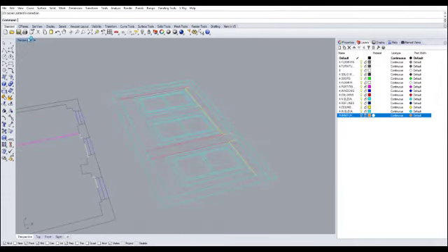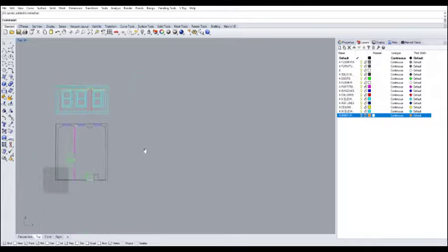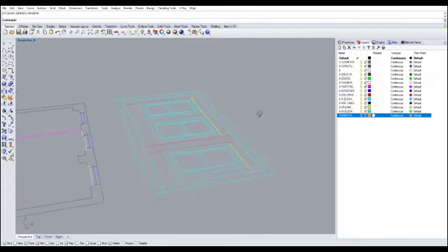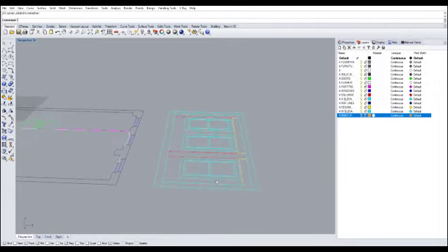So that's an important distinction to remember. When you're on the top view, let's go back, double click. To pan, it's just simply right click and drag. You don't have to press the shift key. However, if you want to pan in the perspective or 3D view, double click it. You have to be able to right click and shift. There you go. So now we're ready to flip or rotate our elevation view, so it will be in the proper orientation to use its information.